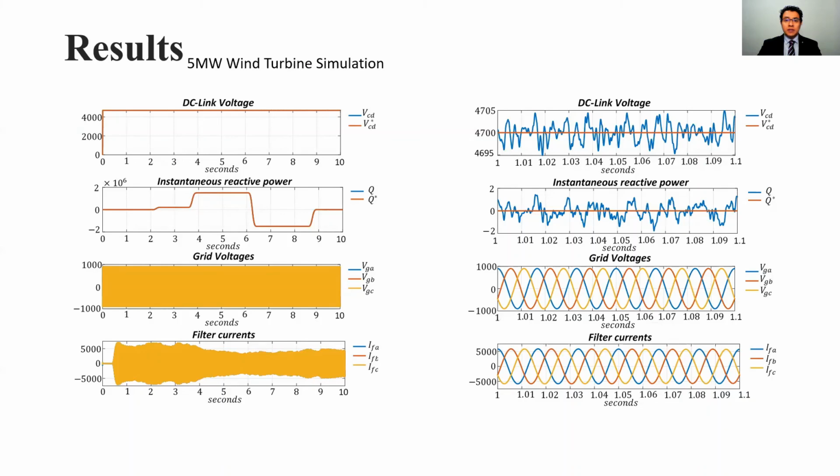These other graphs depict the behavior of the grid-side converter. We can observe that the DC-link voltage is close to its desired value. The reactive power follows the trajectory demanded, representing a supply or a demand of reactive power from the electrical grid.